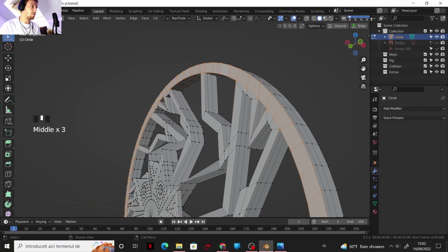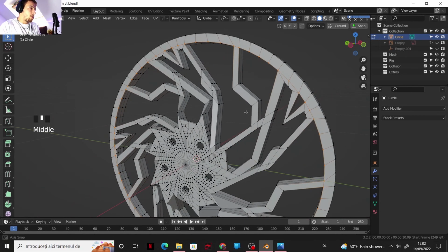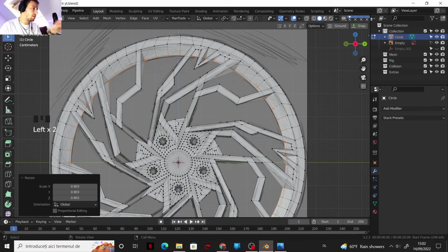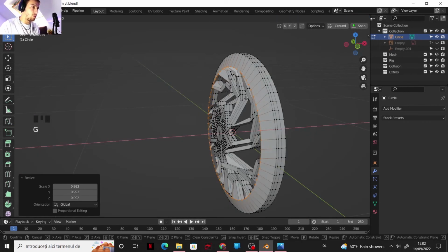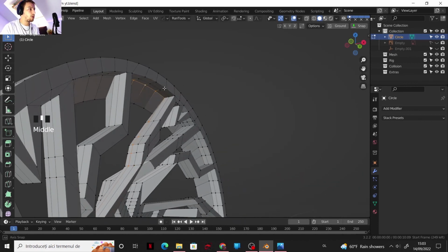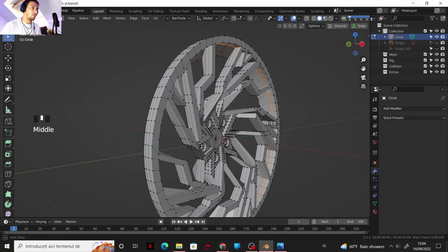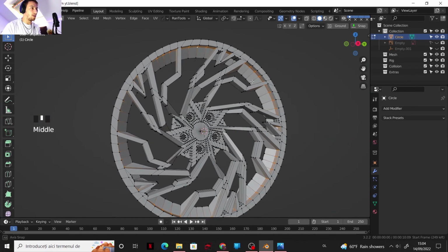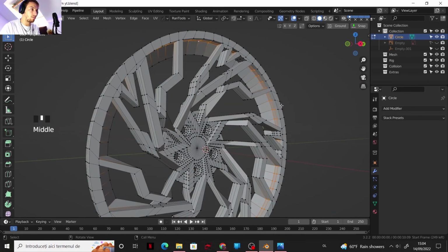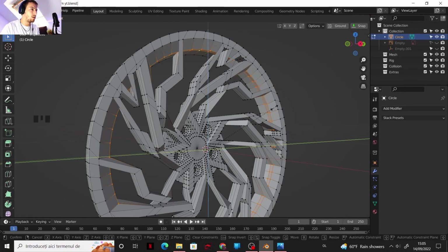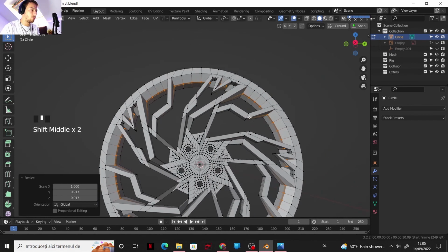Okay, I'm gonna select this edge. So this here can be scaled. Let me check the reference. And this is gonna be moved inwards. Now I need to select also this edge. Okay, so now with this edge selected and anything else staying the same, I'm gonna press S for scale and shift X so it's not scaling on the x-axis, and bring it somewhere like here.